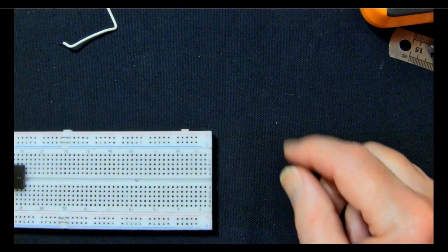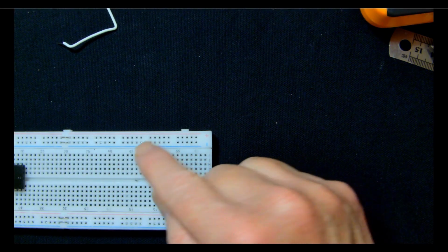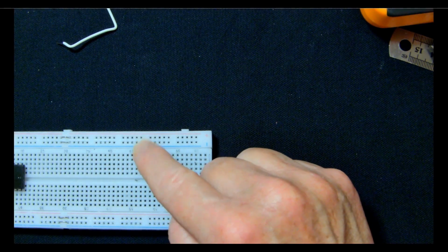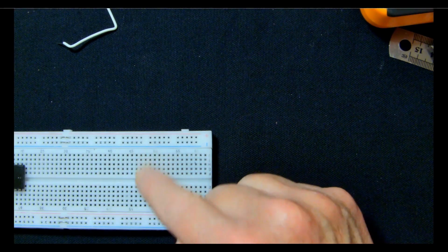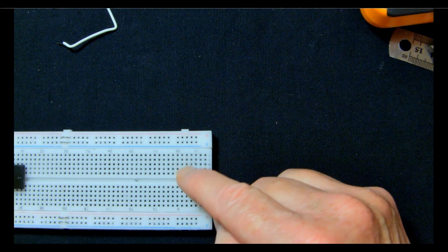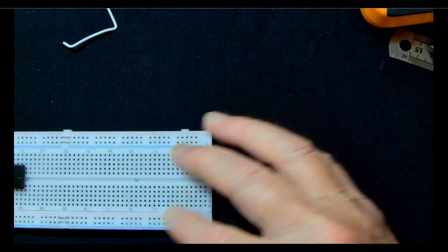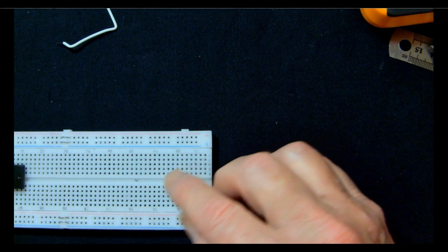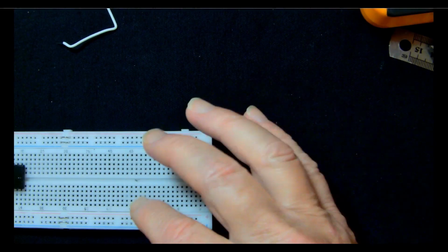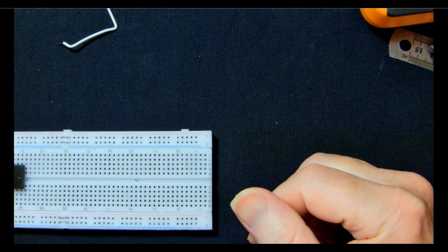Dead bug wiring is where you mount all the components upside down, preferably on a little ground plane that you connect to the 0 volts, and you put some hot glue or some sort of stickiness on them to keep them there on an insulated ground plane. So not directly on the ground plane, but on an insulator, and then you can wire all the little legs together. It's not nice, but it might work.